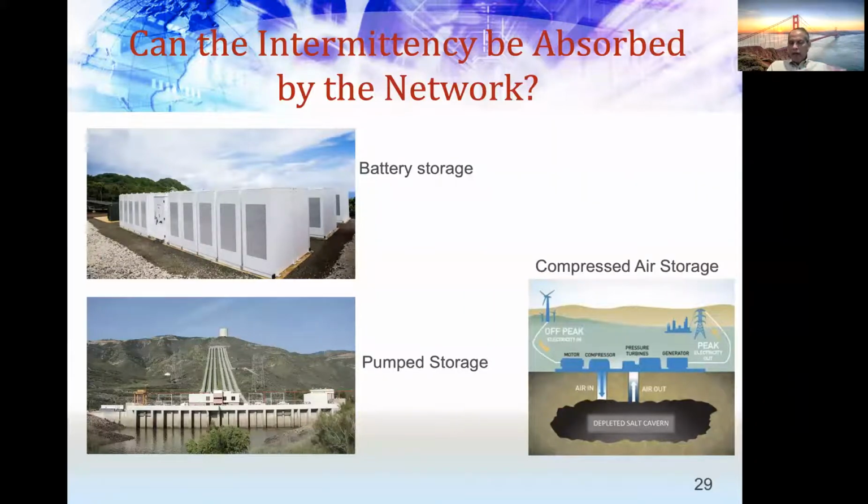Then the upper reservoir depletes, and after some time, you don't have much left, and you are now done. Peak hour is over, so you can start again after midnight. When the demand is low, pump it back again. That is called a pumped storage hydro plant. You can imagine it's a mechanical system. When the water is coming down, I've been to this plant in Virginia.